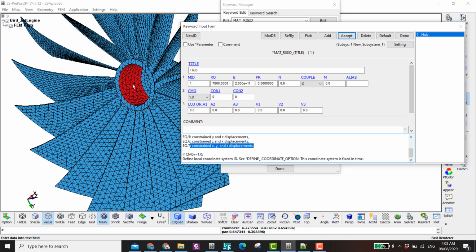This should not be able to move in any direction, it should only be allowed to rotate in Z. And this is constraint 2, so it should be equal to 4, because it's fixed in the X and Y rotation, but it's allowed to rotate in the Z direction.